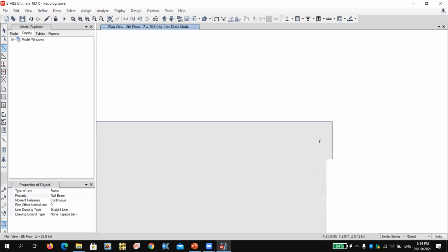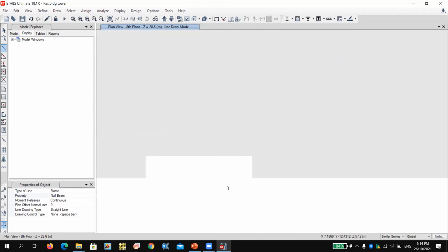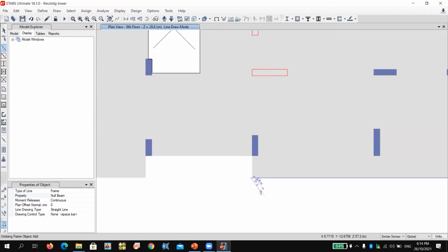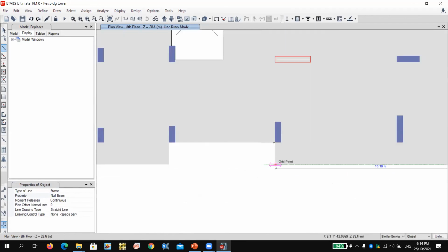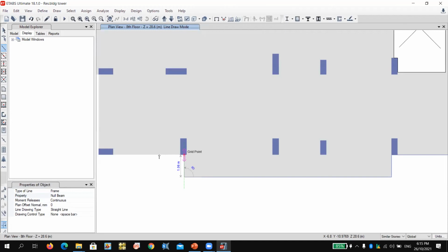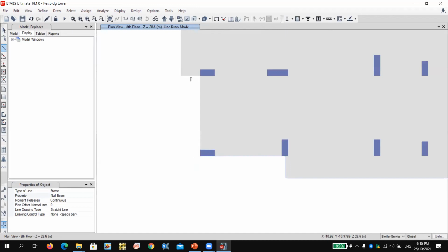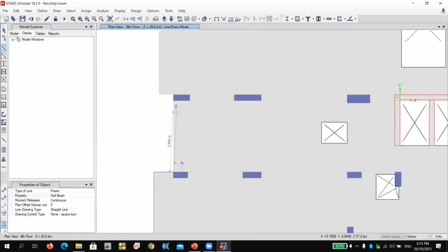And we're trying to show you how you need to design a realistic structure. This point, continue, and continue. Okay, and continue putting the beams on the peripheral boundaries or edges of the slab. Remember, we are putting them in typical stories, which relates to the similar stories shape.